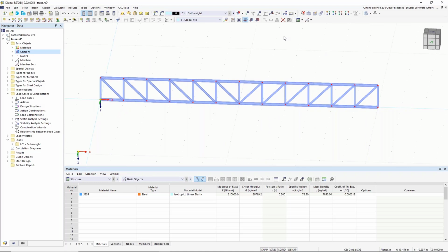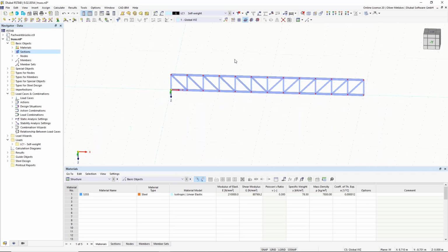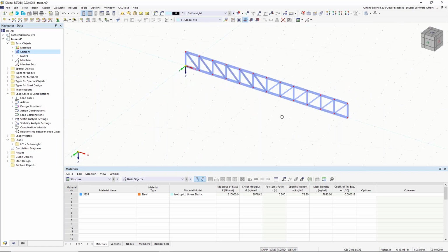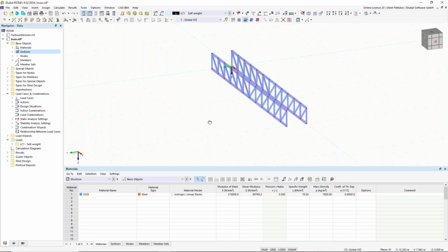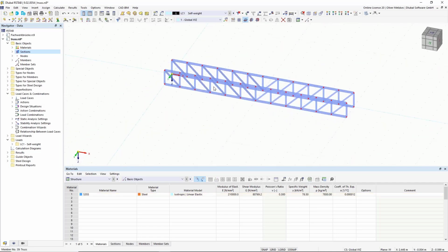Okay, good. So already I have half of my structure here. And now I want to copy it again to have the second half, and I will do it again by using drag and drop, because I know that the grid points in this direction are spaced every 1 meter. So as I want to have 2 meters of width, I can simply pick it again, use the second grid point here, and pressing Control key, then I can release it and it's copied again.